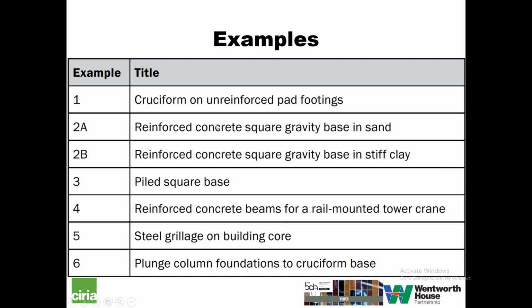a reinforced square gravity base in sand, a reinforced square gravity base on a stiff clay, a pile square base, reinforced concrete beams for a rail mounted crane, a steel grillage on a building core, and plunge column foundations to a cruciform base. Now, as far as I'm aware, there is no other published data on the design of plunge columns, so that in itself is useful and took a lot of research.